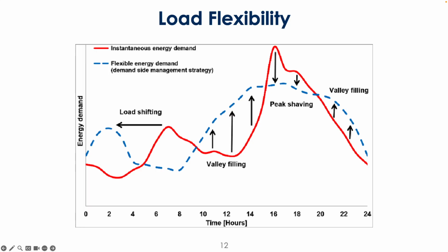For the mechanism of load shifting, there are a couple of terms you might hear. Peak shaving is one type of load shift: when your load is at a peak, you move that load around and shape the peak, so you go from this red line, which has a much sharper rise, and move that load elsewhere so that it drops down and you stress the system less. Generically speaking, we call that peak shaping.